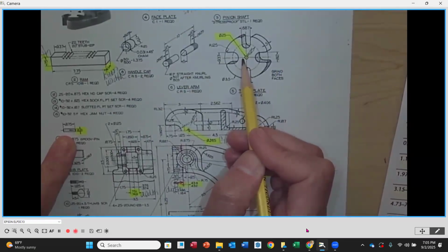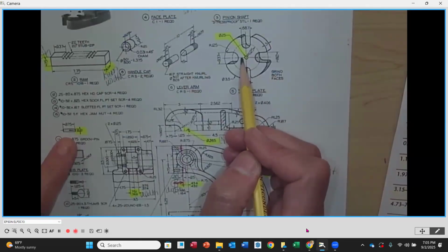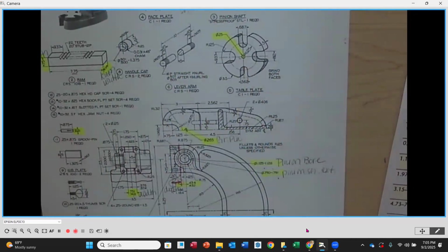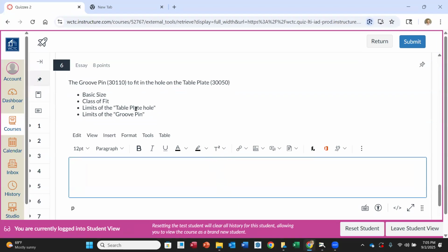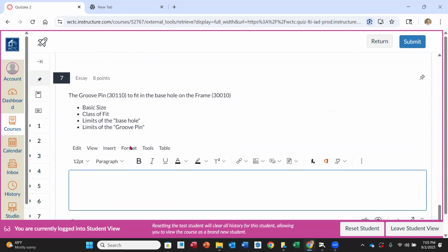This is the subassembly you're going to create, okay? When I talked about it in the assemblies, there's going to be a little subassembly. It's just 2 pieces, but we want those always to be together, okay? So in that case, they're going to be a press fit, okay? So when we go back over here, you're going to be picking out then the appropriate fit. So it's going to be an FN something, right? FN something. So you can read the descriptions and see what you feel is most appropriate.